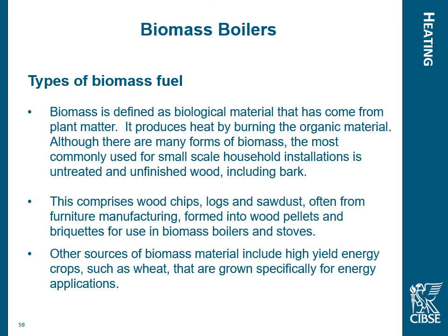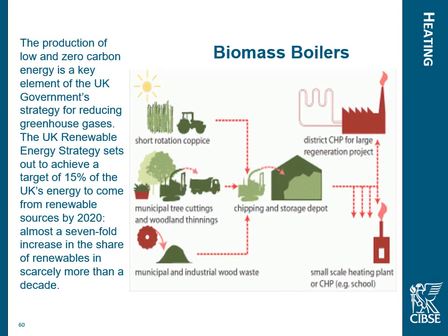Biomass is defined as biological material that's come from plant matter, which produces heat by burning this organic material. I think what can work well with biomass though is in rural areas where we've got rotational crops, municipal tree cuttings, industrial wood waste going into a local chipping and storage depot, powering a district CHP, and then that in turn powers schools, commercial units and houses, etc.